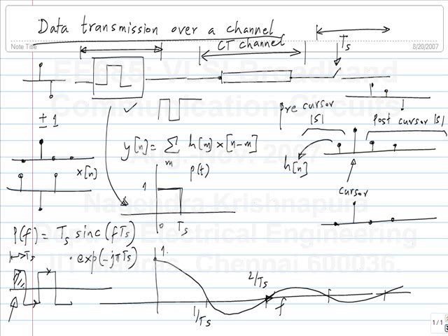So the Fourier transform is you take every sine wave and you see the amplitude, you multiply it by the signal and then integrate it. Okay, that gives you the best RMS fit amplitude or something. That is you minimize the mean square error between a signal and the sum of sinusoids, and the resulting sequence that you get is the Fourier transform.